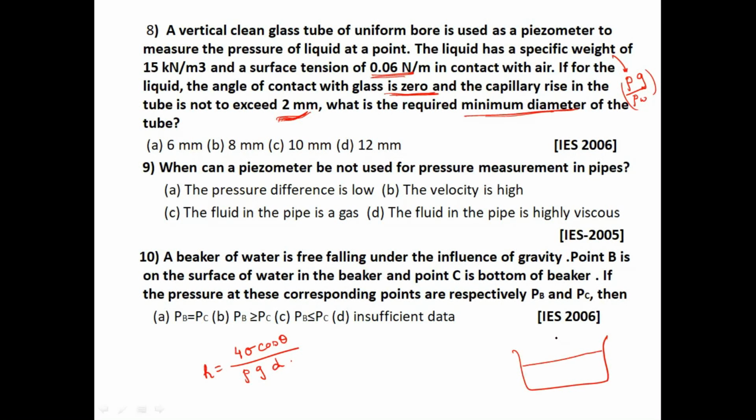Take one capillary tube. Surface tension sigma is acting, so sigma into pi d, the circular portion, into cos theta is the upward force.